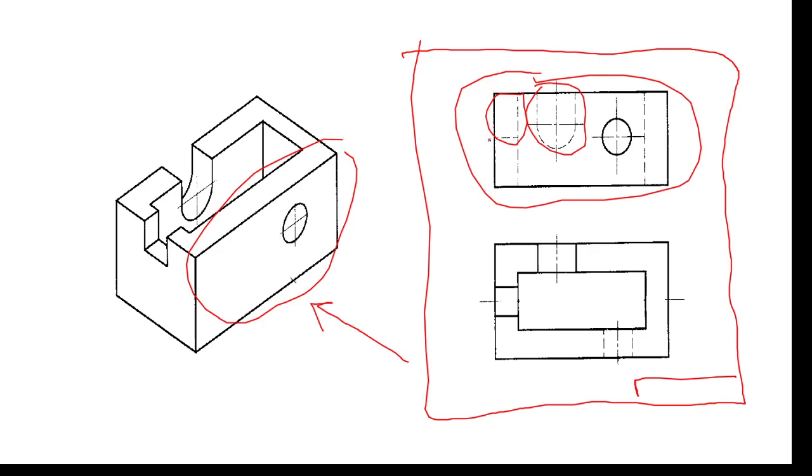We need to show the height of this channel, the distance from here to there, such a dimension. It is not allowed on this normally created view because the image of the entity is in dash form, the entity is hidden. I can say similar things for this channel. It is the only view on the picture plane to show the dimension, but unfortunately the entity is hidden.